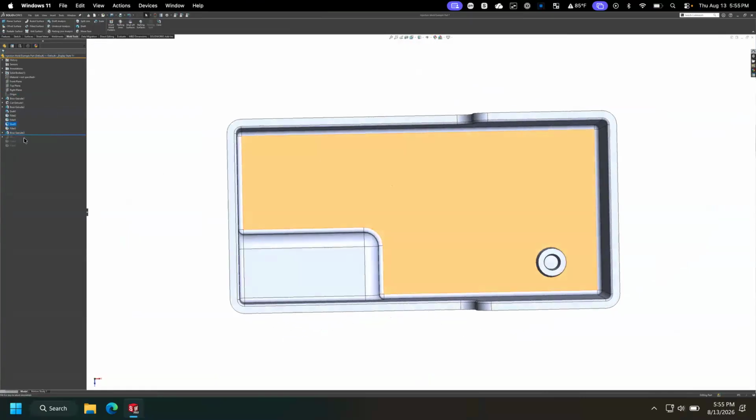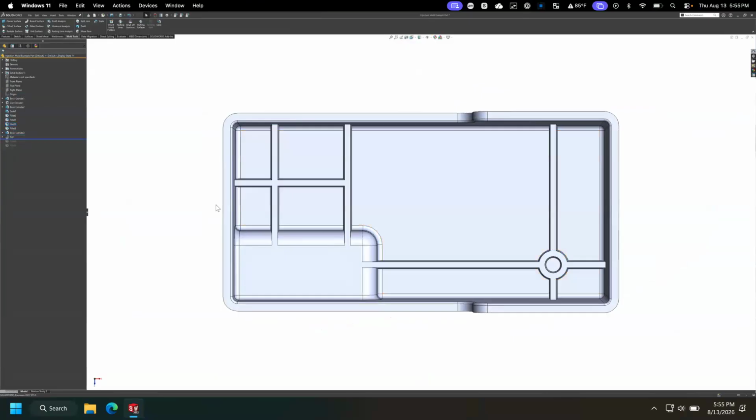to create some ribs here. So when you're designing for injection molding, right, we can't have a solid part that's just a big block of plastic, but you do still need structural rigidity, often with parts. So the way you accomplish that with injection molding is by ribbing it in such a way where you still have that rigidity while not having a solid block of material.